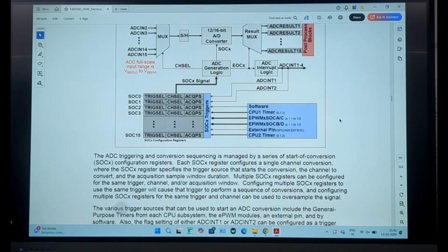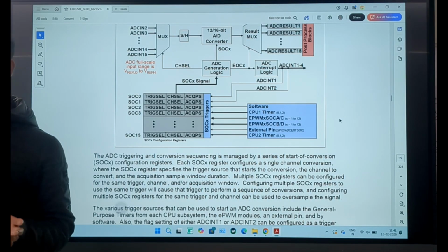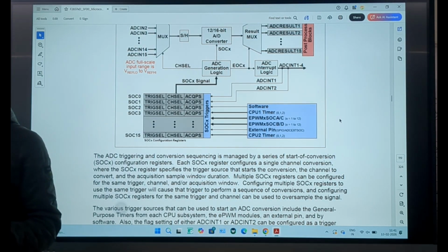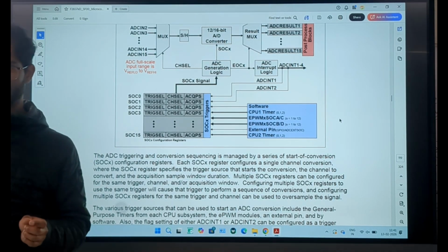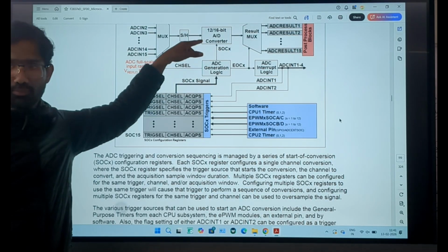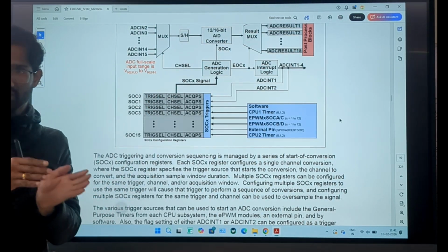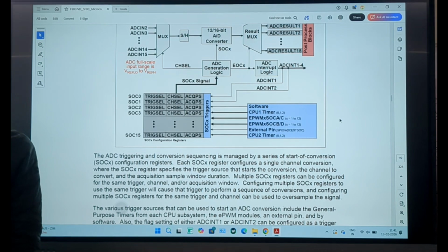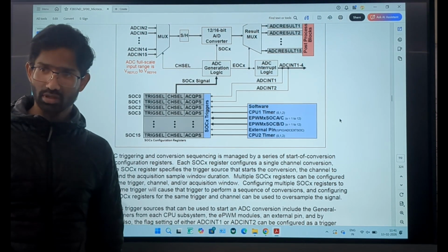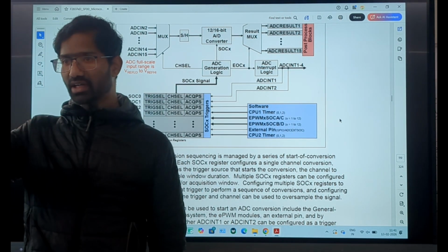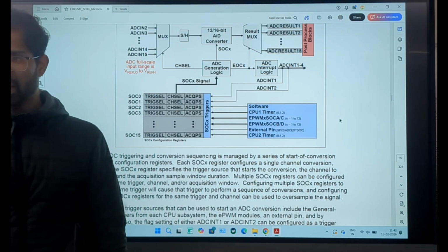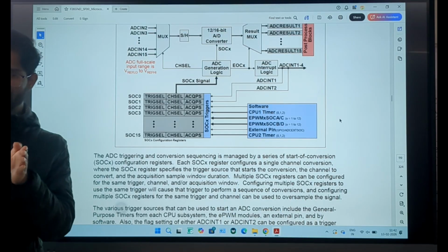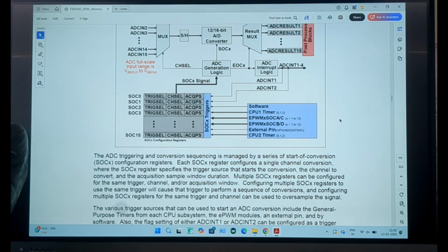Whatever the microcontroller sees will be discrete values, not continuous values. It won't sample at irregular intervals; it will be doing it at periodical intervals. So periodically you trigger an SOC pulse, so that it converts at that instant and saves to memory. You won't get noise or unwanted values, and you will get sampling at regular intervals.